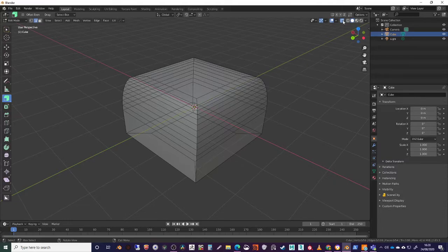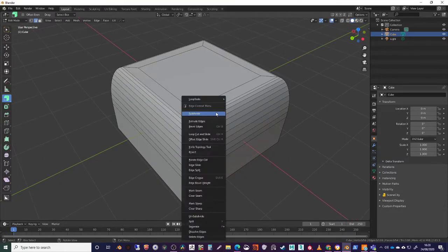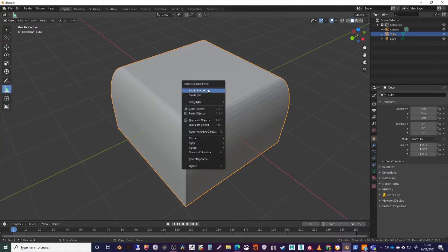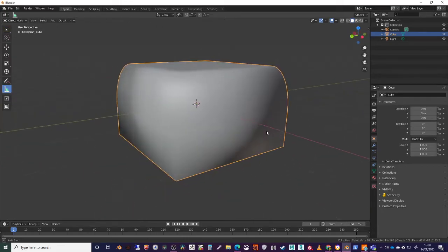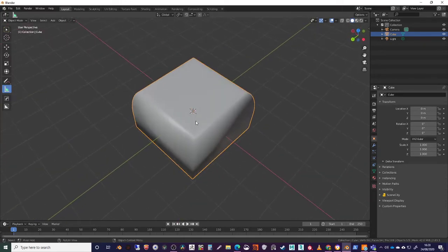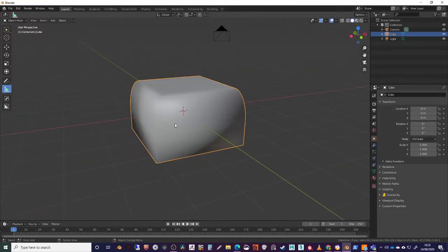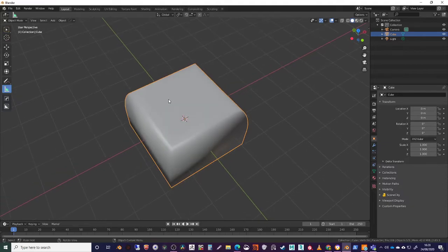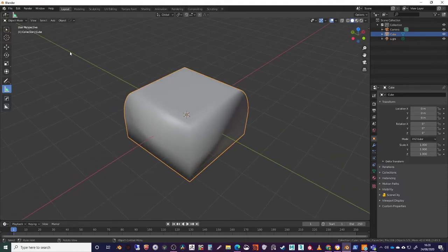And if I go out of my shader mode, go into object mode, right mouse click on this and say shade smooth, you see we've got some smooth shading happening on there as well. So we've got the smooth shading happening. The hard edges sort of disappeared, so we would need to address those with maybe some creases and work with those. So that's how we move around inside here.